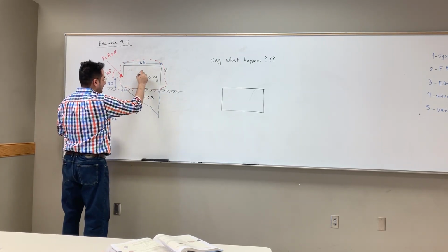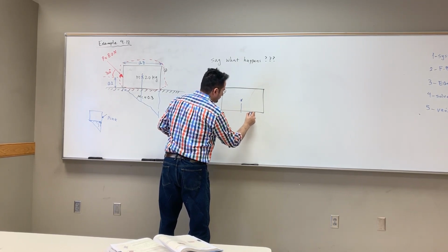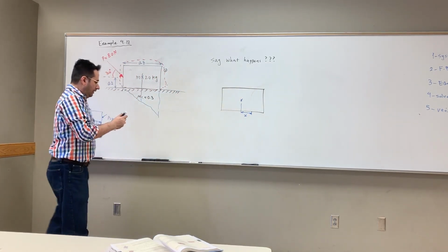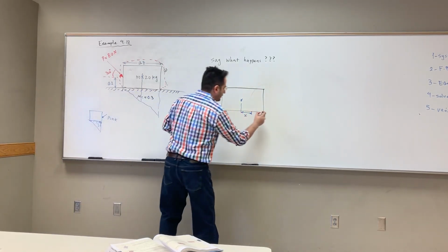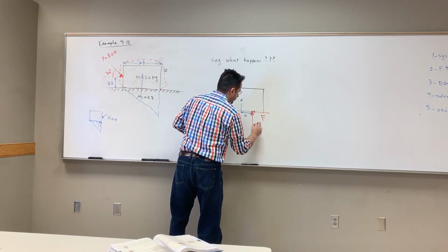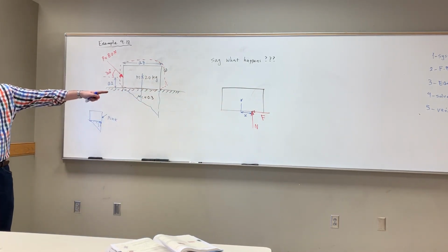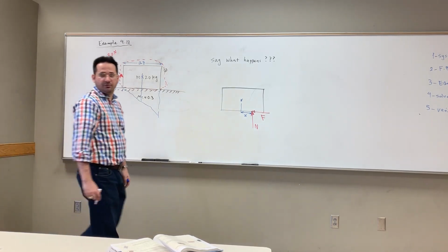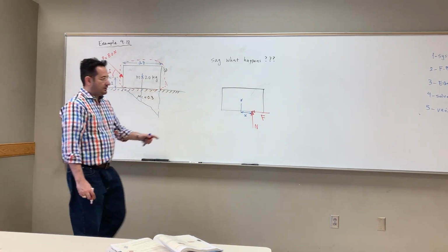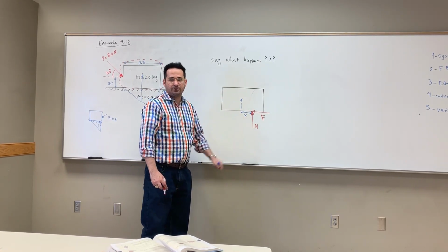So let's just pick a center, and put the force at an unknown distance x from the center. I put the total resistant friction force and the total sum of normal forces. So those are two unknown components, plus an unknown distance x. How many unknowns are introduced by just this friction surface? Three: a location that I don't know, a friction force that I don't know, and a normal force that I don't know.